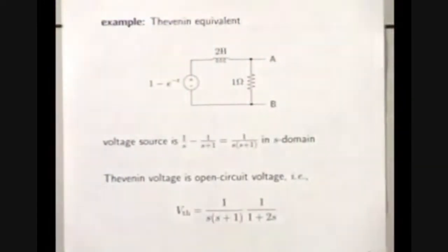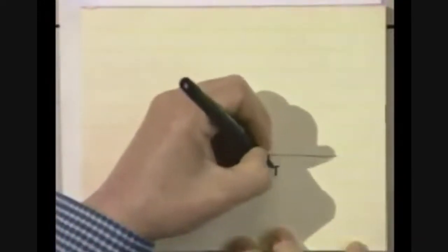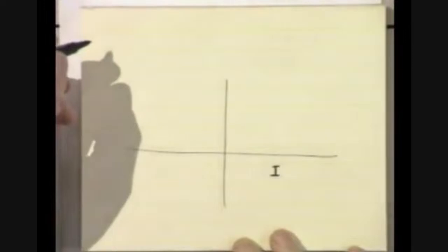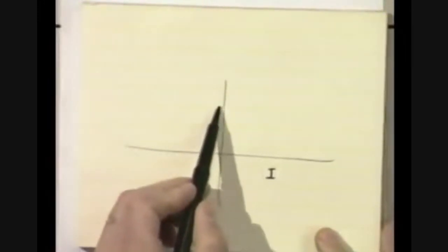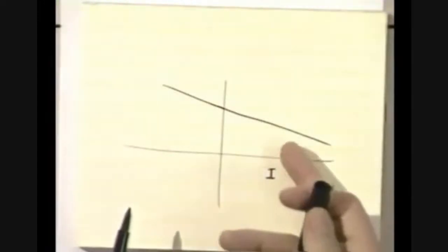It's not hard to explain to somebody. What you do is you draw various amounts of current out of this battery, for example, and I measure the voltage, and the voltage looks like this or something like that. And that's the VI curve, and you say, okay, that's the Thevenin equivalent. It's a resistor in series with a voltage source. Okay? This seems pretty simple.